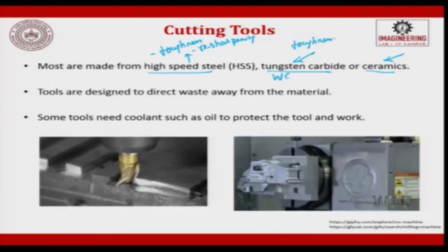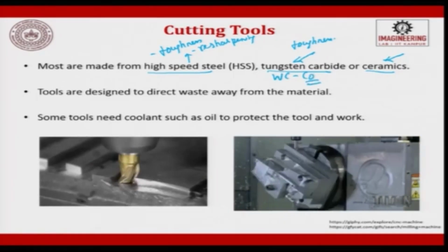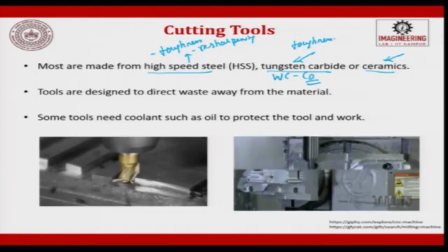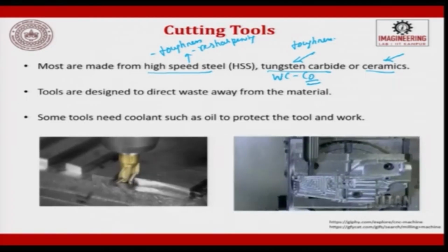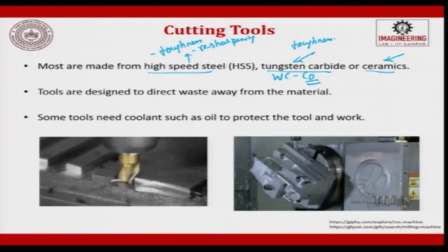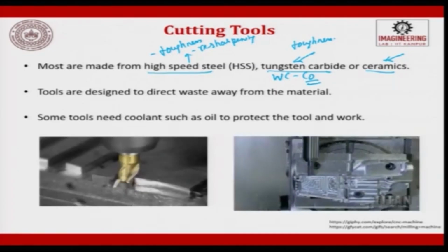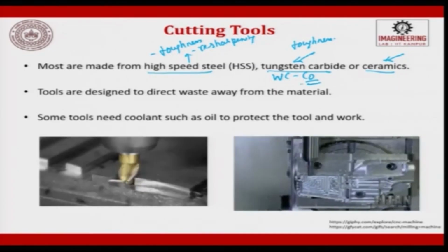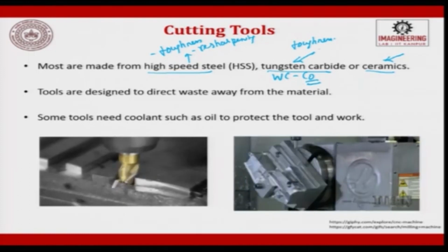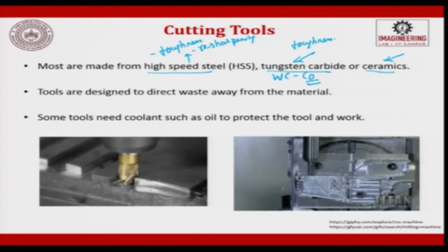If you take tungsten carbide cobalt, the toughness is given to the cutting tool by the cobalt. When machining happens, the workpiece is rotating and when the tool comes in contact with it, it is an impact load. So, toughness has to be very high. Wherever there is a lot of impact load, we go for tungsten carbide cobalt.